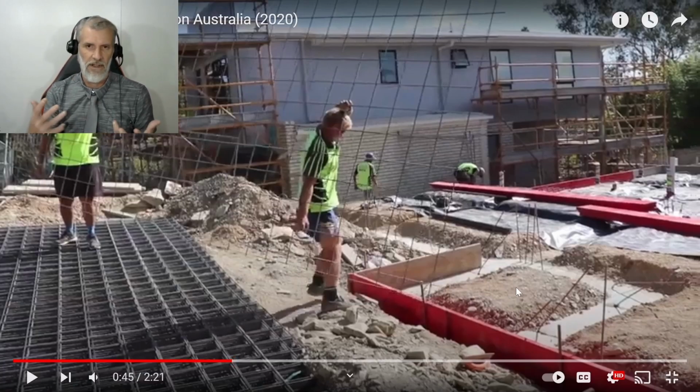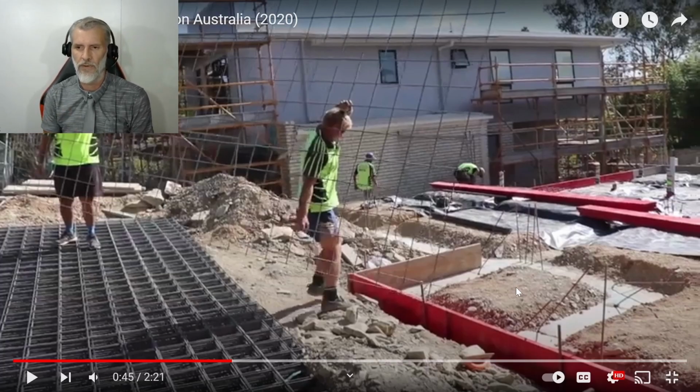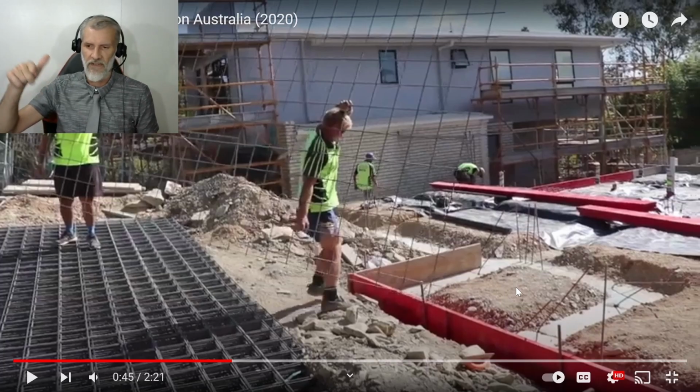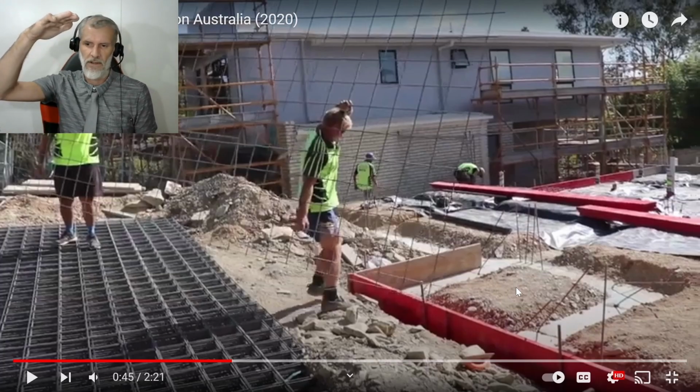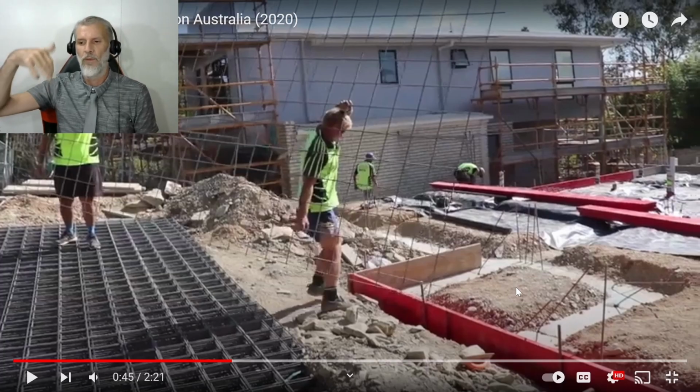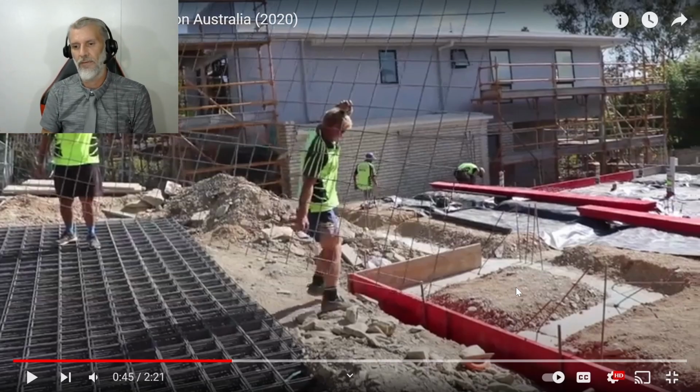Okay, so you can see there, if we just go back a second, so they're filling in with dirt here. So that would be compacted, but it wouldn't be compacted the way that I saw that was happening in Germany. But you can already see that the footing is already a metre deep, and then we're going to put on top of that the 200, 250, 300 on the edges, so 300 of concrete.